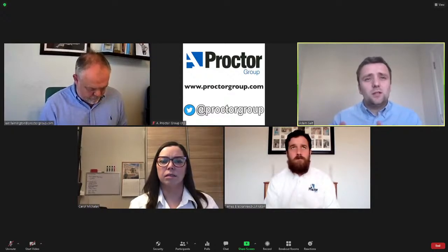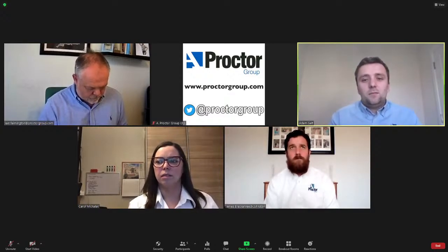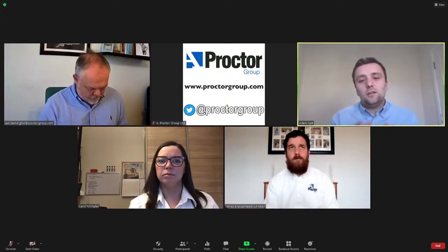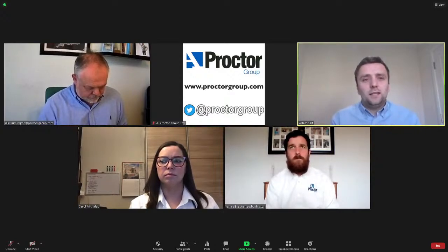You then also have to consider what type of lifestyle you live. For example, if you're the type of person who constantly goes in and out of your house, you go to work, you come back, have some dinner, you take the dog out, you then come back, get ready to go out again for the evening, then you're more suited to internal insulation. And that's because you've got a lower thermal mass internally. This means you get a quicker response from your heating.